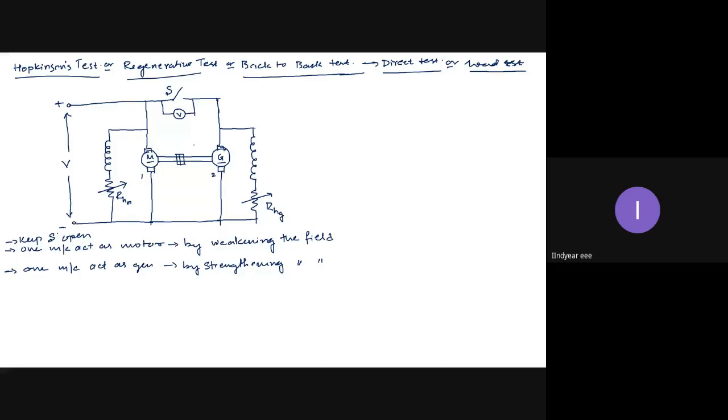Okay. Now, what is the function of the supply voltage or supply terminals when there is a back-to-back generation or regeneration of power? Once after the first cycle or first excitation of the motor and generator, the supply can be taken out if and only if both the machines don't have losses. But we know practically DC machines have losses.